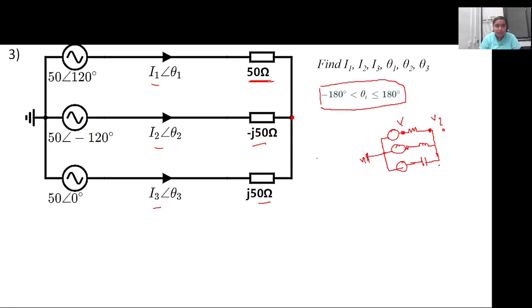So you're going towards the right approach. Can you suggest what you have to do? By using KCL, ma'am, nodal analysis. Yes, exactly. If you can figure out the voltage at this particular node, you can easily calculate all the branch currents. So the best option would be to use KCL.